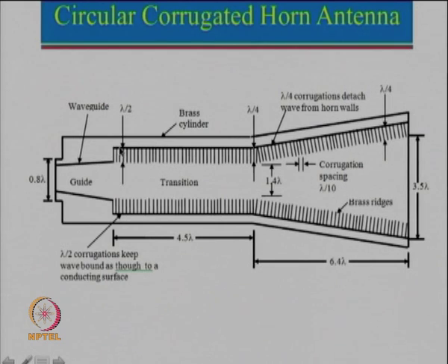See over here, it is a short circuit, and if this dimension is lambda by 2, if we apply transmission line theory looking from this point, transmission line theory says if the characteristic impedance of the line may be anything, but if the length is lambda by 2, then the load impedance becomes the input impedance. So the load is short circuit, it will also become short circuit. So if this particular depth is lambda by 2, this whole thing will act as a short circuit, even though it may not be a short circuit. But that is really not at all a useful thing.